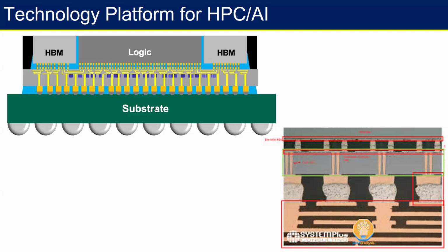Okay. And now this organic substrate, obviously it has to connect these wires, whatever were there on the board, through the substrate to this. So that means some materials are again needed through the substrate. Obviously those would be wires passing through this substrate, which are through vias, right? Because we have to put them through this substrate.